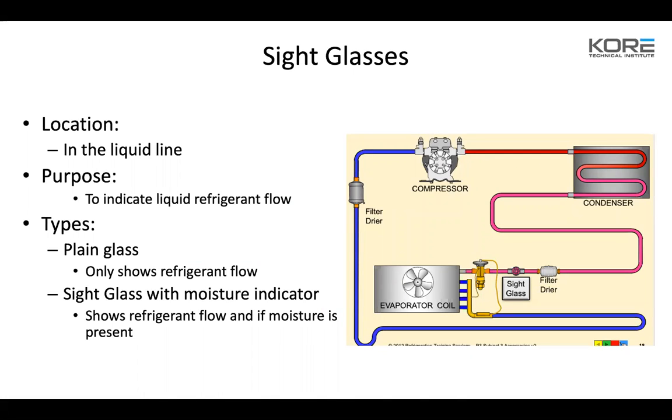So let's talk about sight glasses. Location on the liquid line. Do we put the sight glass before or after the filter dryer? It kind of gives it away here on the picture, but we always do it after the filter dryer.